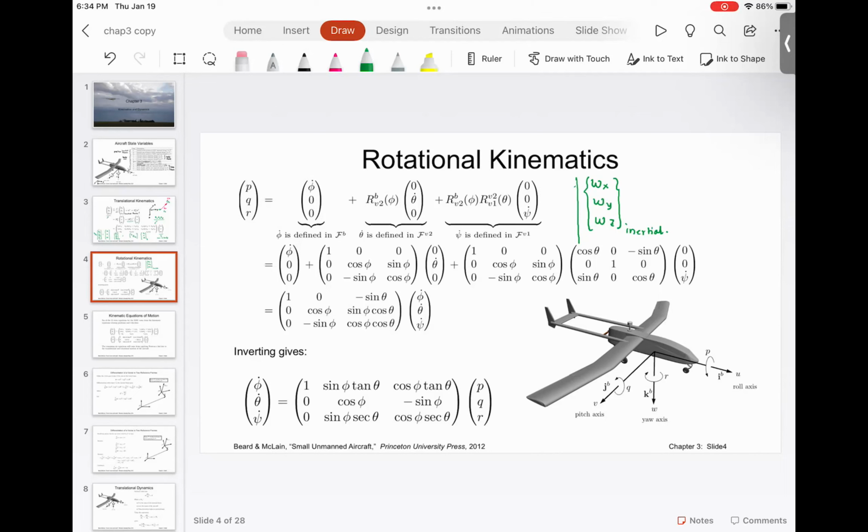Yeah, because GPS data comes to us at 20 hertz, which is 20 times a second. But the accelerometer data we get at 1000 hertz. So the aircraft flight control system cannot update the control surfaces at 20 hertz. They have to update the control surface. The solution has to be computed at minimum 1000 hertz, 1000 times a second. Otherwise, the aircraft will go out of control. So we have an external solution that is coming at a much slower update rate, but the internal solution we are calculating at a higher update rate, and then we use the external one to correct our internal solution.